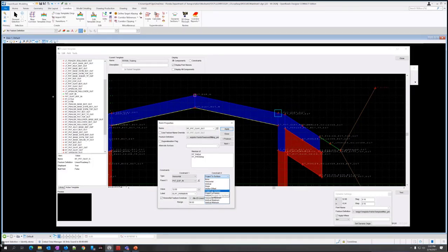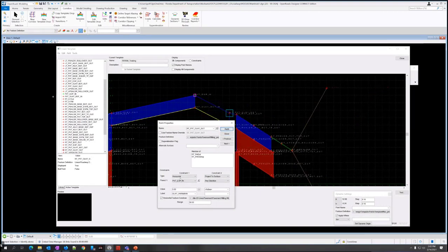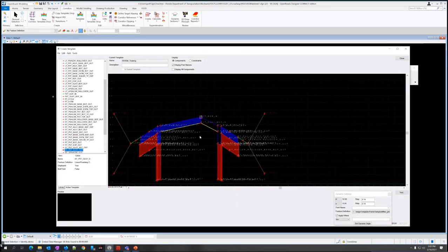Changing the projected surface. Just looking at the picture to make sure everything's right. So the value here, we need to select active. So this will be the active surface. And then click apply. Oops. We lost my horizontal settings. Change that and click apply. Okay, it looks right now. And I can close it.